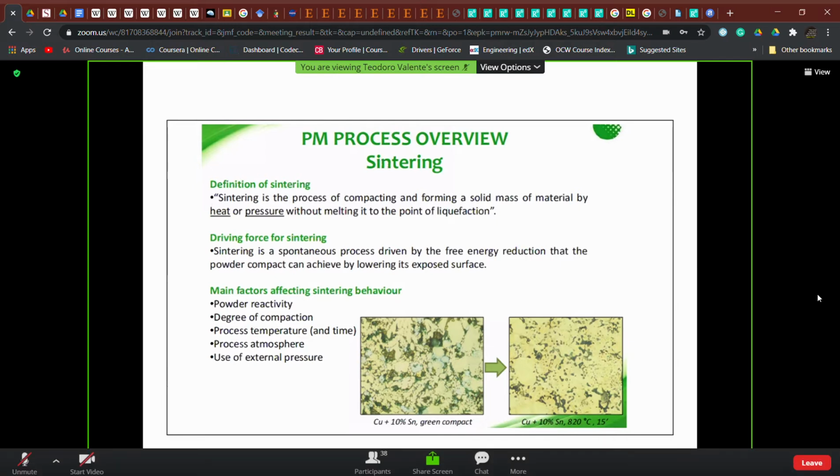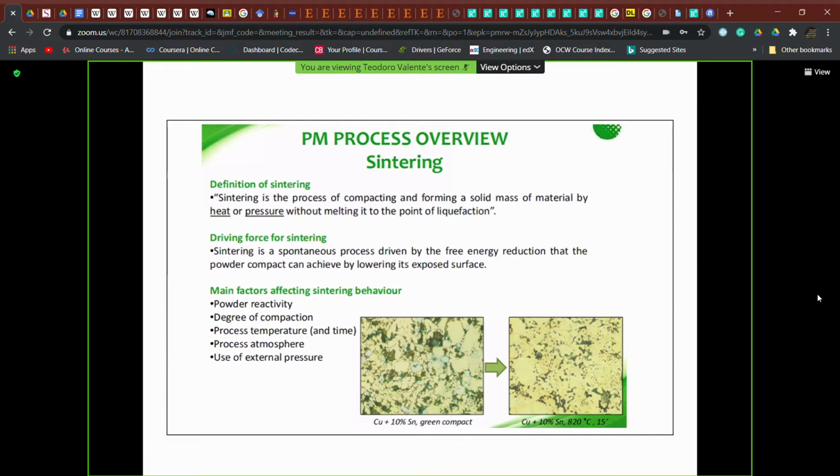And after, in this case, just 15 minutes, so this is not an optimal time for this alloy, anyway, you can see how the black areas are reduced due to the fact that solid state diffusion is able to enable mass transportation, thus recovering the initial voids. And for this reason you can also expect shrinkage after final compaction and final sintering.